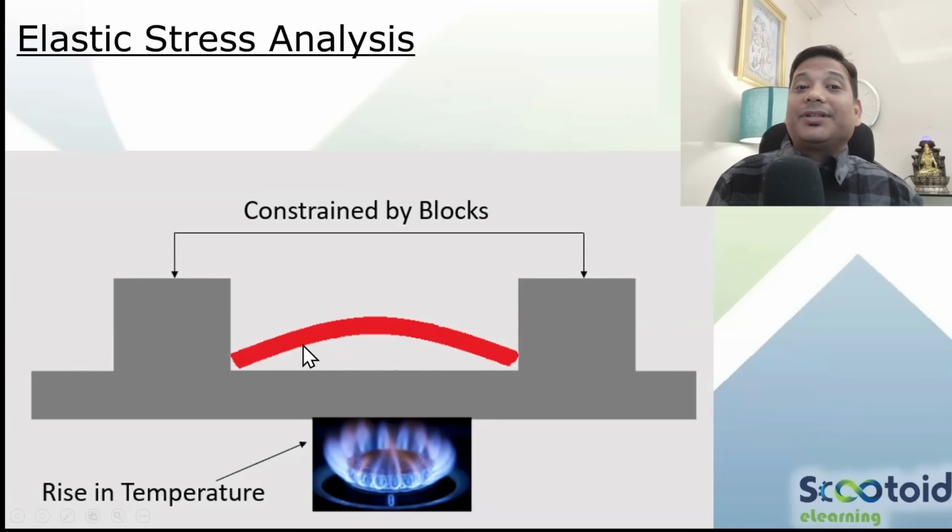They reduce the stresses by deformation. Once it is deformed, the stresses will come down. Because of this self-limiting nature, secondary stresses are allowed up to twice the yield value, 3 times our allowable stress value, which is twice the yield. So we can go up to that point.